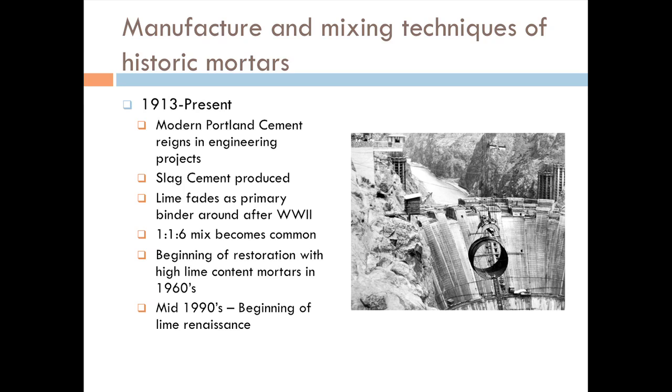And then you get something called 116, and that becomes the mix for building all masonry in North America. 116 stands for 1 part lime by volume, 1 part cement, and 6 parts sand. So if cement's so great, why would they add lime? Because cement is a very dead material. It doesn't work. It's burnt to a crisp. It's turned into a glass. It doesn't have flow. It's not very friendly to use. The practical applications are limited when laying a brick. A mason would be screwed.